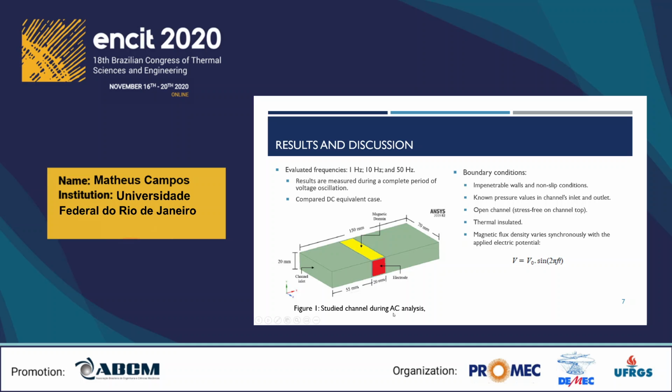As boundary conditions for these simulations, we use impenetrable walls and no-slip conditions for the channel's side walls and bottom, and for the channel's top we use a stress-free condition. For a critical case we use a thermal condition, and consider that the channel is thermo-insulated on every wall.